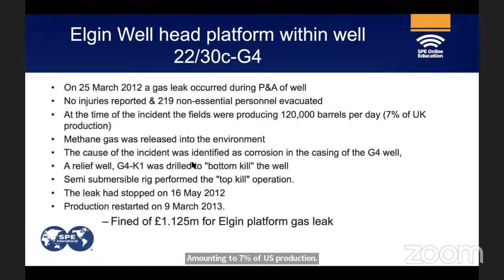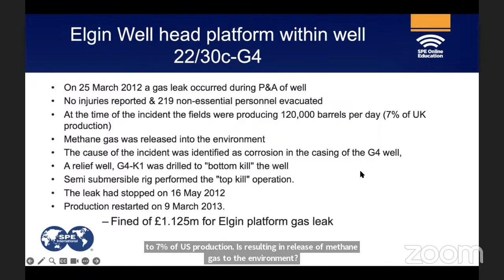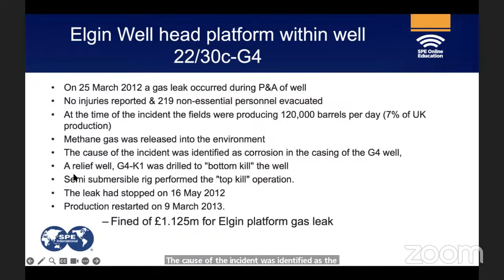The cause of the incident was identified as corrosion in the casing, which I was trying to express. A relief well had to be drilled. So there was an additional cost for the relief well, and a semi-submersible rig had to perform a top kill operation by pumping heavy mud into the well to kill the well. And the bottom kill was performed by a relief well. So these are additional intervention costs to cure the problem, in addition to the stoppage of production.